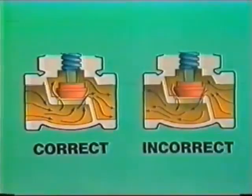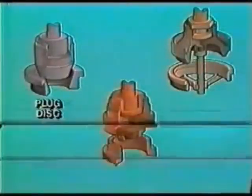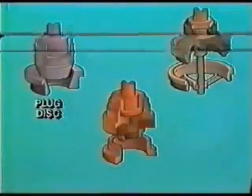Flow from the other direction would put pressure on the top side of the plug and could close it. Globe valves can be equipped with several types of discs, including the plug disc, the composition disc, and the conventional disc. The plug disc is the most common globe valve disc, and it comes in a variety of styles depending on its service.